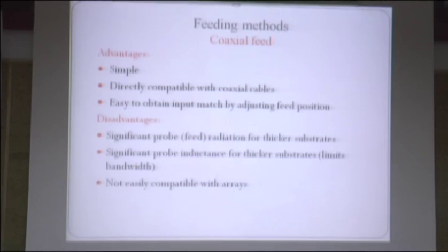Disadvantages. Significant probe feed radiation for thicker substrate. If we use a thick layer of substrate, then radiation by the probe occurs. So this is the main disadvantage of coaxial feed.